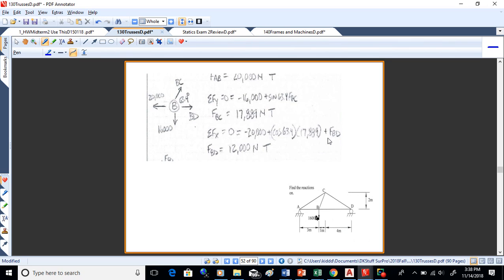All right, the next place I go here is to B. What I'm going to do then is I know I've got that free body diagram drawn for B. Now notice what I did with AB. I know that at A it pulls to the right, so at B it'll pull also, and that'll be to the left. It's like a rubber band that you've pulled between your two hands. It pulls both of your hands inward. So that's what that AB, which is in tension, is doing. It's pulling A to the right, it's pulling B to the left. It's in tension.